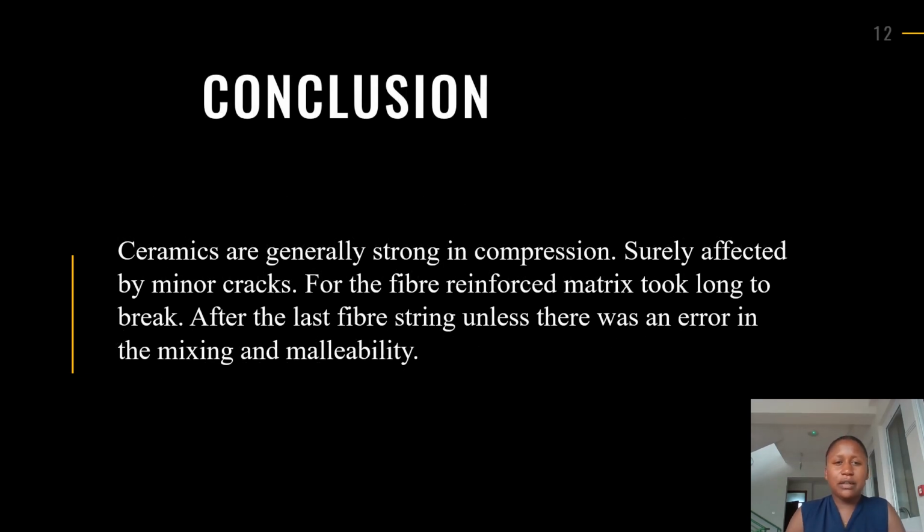So we come to a conclusion that basically ceramics are strong in compression. We noticed it through the results and the discussion that we have. And they are surely affected by minor cracks, like a small crack can lead to permanent damage in ceramics. We also had to appreciate that the fiber reinforced matrix took long to break.